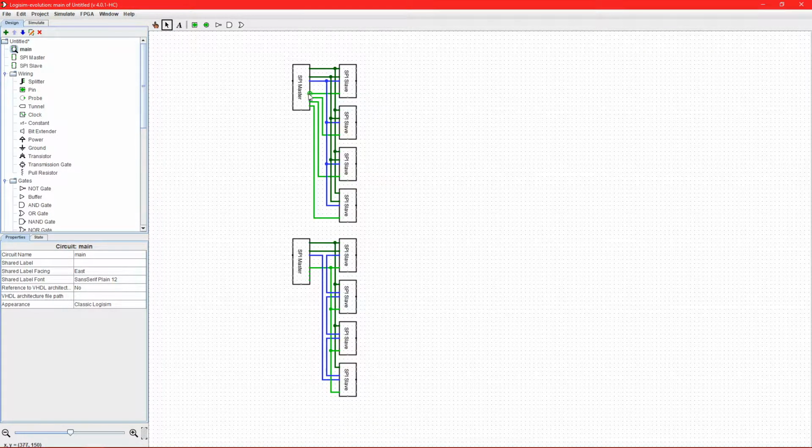So the slave select lines are active low. That means if you put a 0 on the line, then that slave is selected. Now in the case of daisy chaining, we have all the slaves selected or deselected at once.